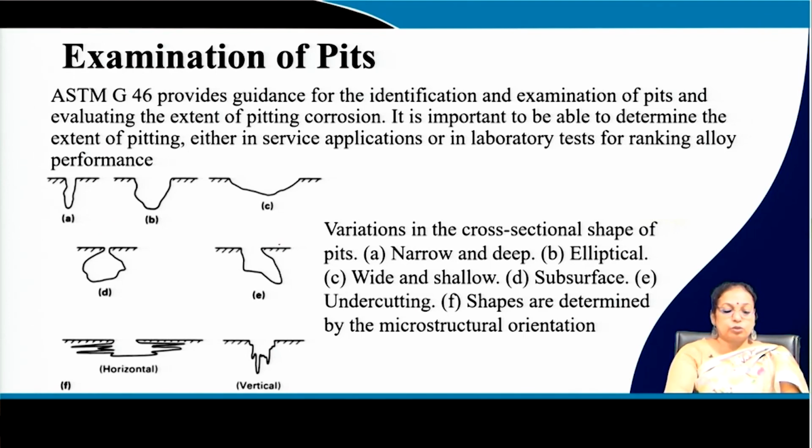You have to do the surface profiling and subsequently see the volume of the material loss due to pitting, and then you have to take the average of the same. So, it is a very tedious job. Better would be to try to establish the pitting corrosion resistance in terms of critical potential for pit formation and critical potential for pit growth.